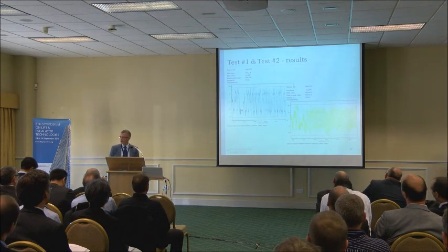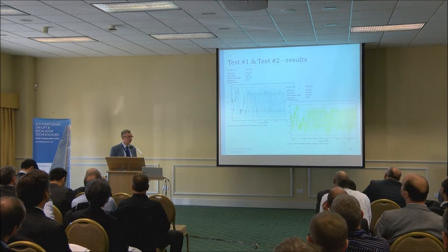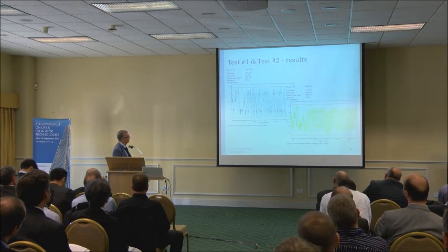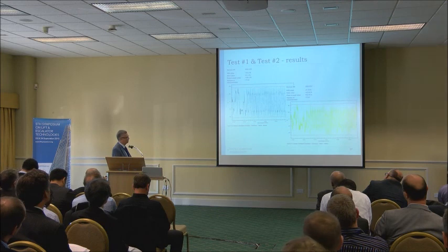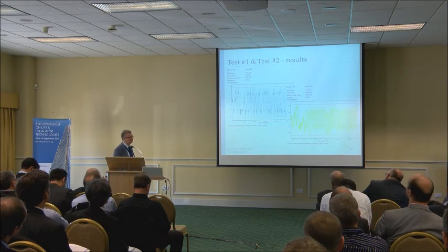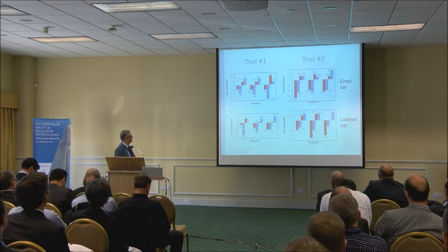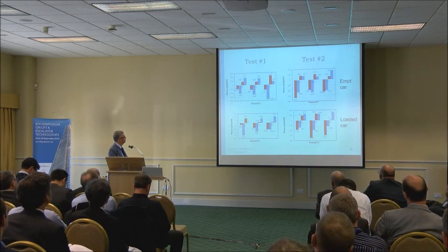And we collect all the points during the safety gear operation, so just running condition, then we trigger, then the safety gear has operated, and we collect the force values.